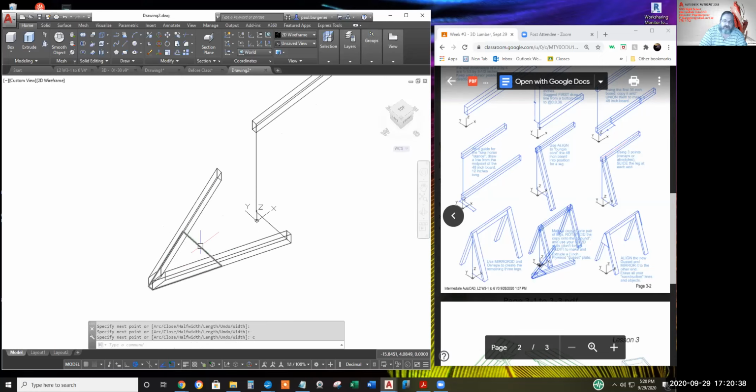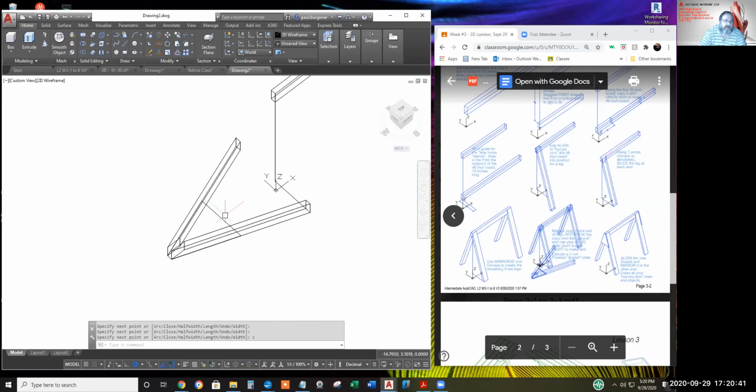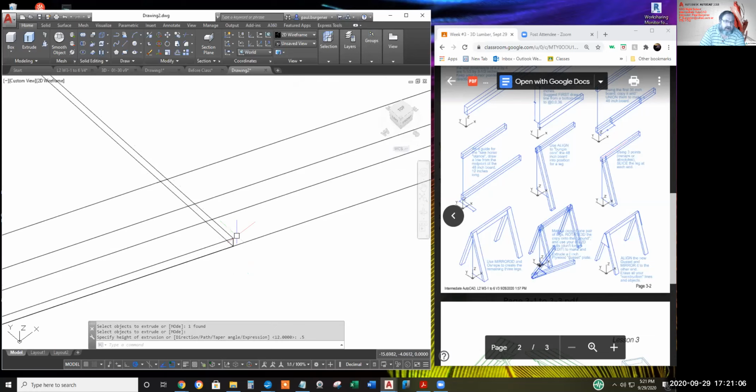Now, can I extrude this straight down? I think I can. Extrude, select the polyline gusset plate we had, hit enter, slide my cursor in the negative Z direction. How thick's the plywood? Does my handout say 1/2 inches we got left at this construction site? So I'll type 0.5 and hit enter. And darn it, why did it go up instead of down?